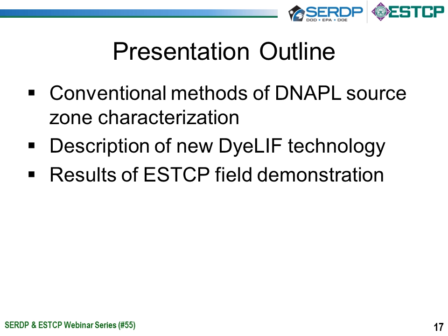My presentation outline today is I'll share a few words just on conventional or traditional methods of DNAPL source zone characterization that we've had available to us, and they have unfortunately been lacking. And then I will describe a new technology, a variation of laser-induced fluorescence called DyeLIF, and then I'll present the results of our ESTCP field demonstration.